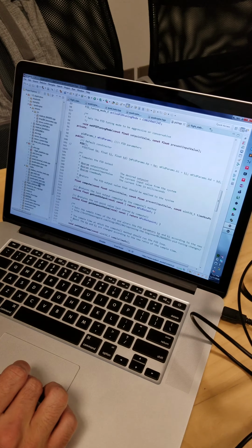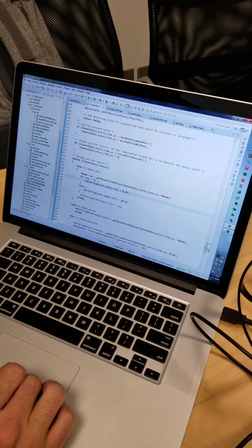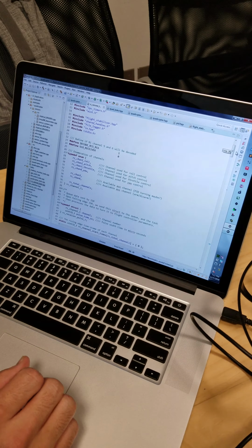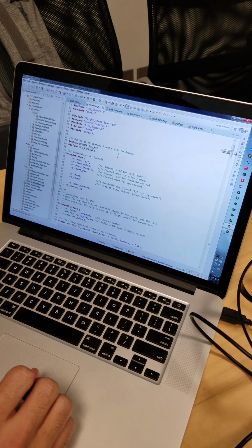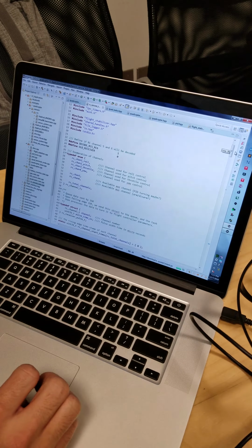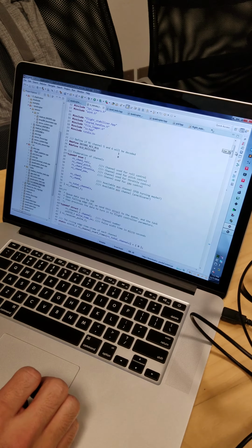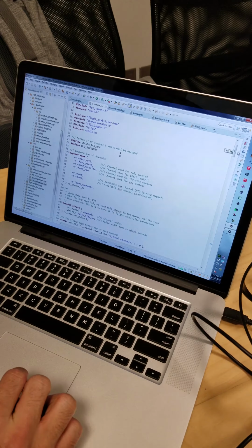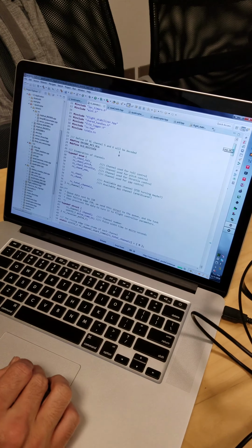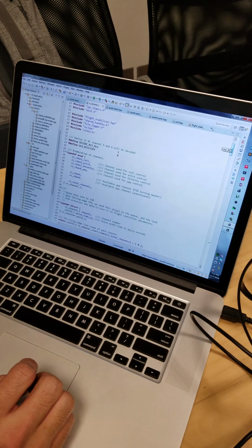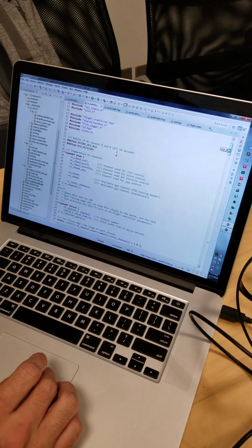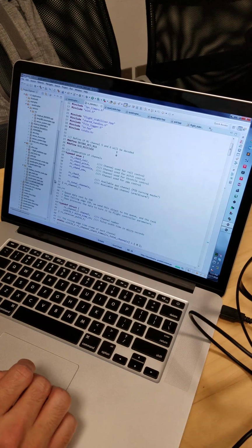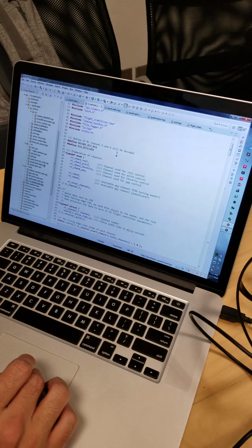And drilling down to some more tasks, we have another RC remote task. What this is responsible for is, during manual mode, we have GPIO interrupts that trigger off of a remote control receiver. And so this task basically checks the duty cycle that it receives from the transmitter and calculates what the throttle is or what the requested angle is. And then at the end, it applies this to the flight controller angles of the quadcopter class.